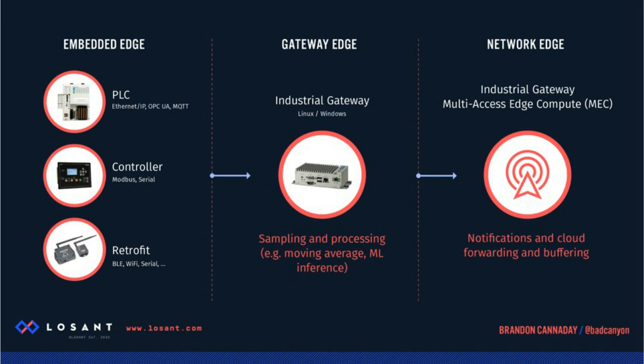They can forward all that data to another gateway, basically the exact same hardware, and that can do essentially store and forward buffering. That's the primary use case, so that if your internet connection does go out, it's surprisingly common for someone just to forget to pay the internet bill. So you want to be able to store that information. That way, if the internet does go down and comes back, your cloud side doesn't lose anything.